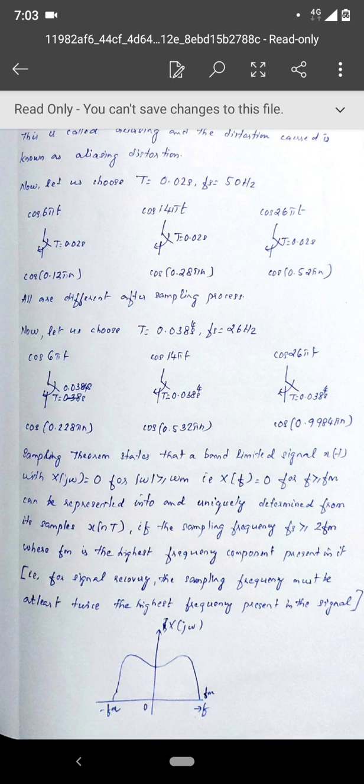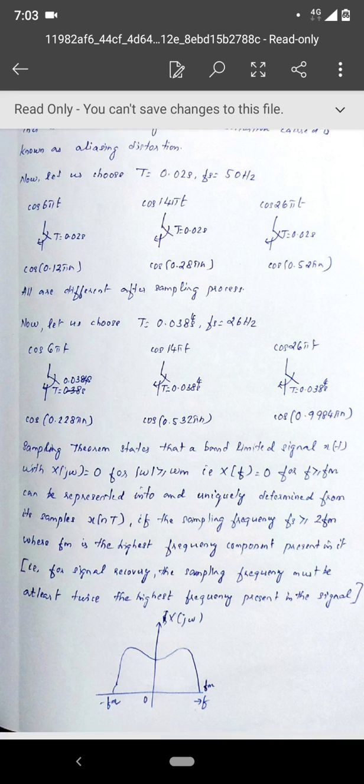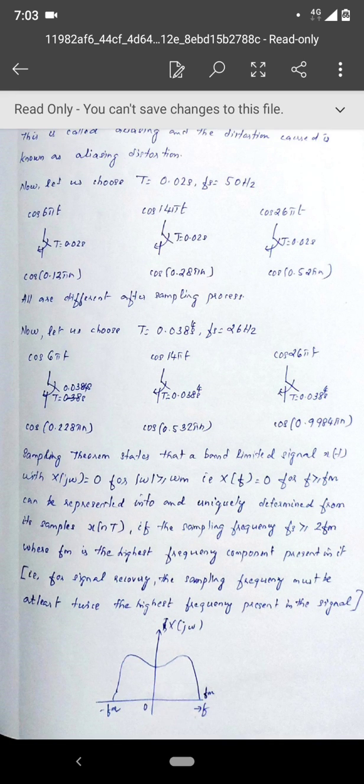So that is the point I have to make. Here you can see again that the three signals are distinct. The highest frequency component is just cos pi n, because we took the highest frequency component, doubled it, found the sampling interval and applied it. So the cos argument becomes just pi n.